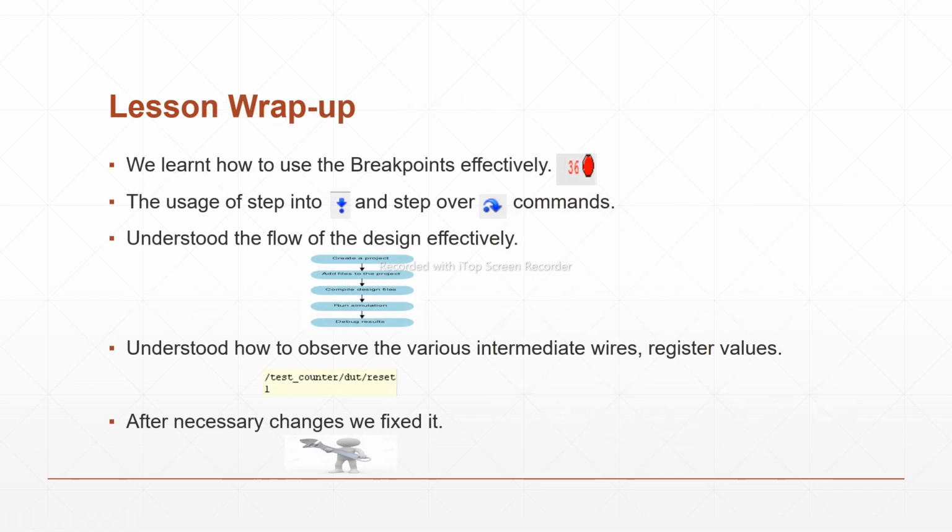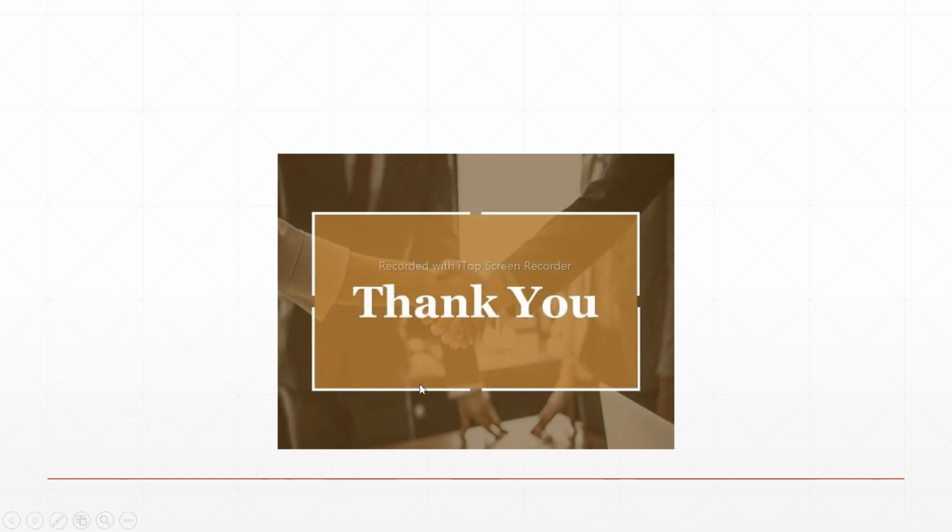So the lesson wrap up is that we learned how to use the breakpoints effectively, and how we utilize the step into and step over commands, and we understood the flow of design. Then we understood how to observe the various intermediate wires and register values. So after necessary changes we were able to fix it. So thank you.